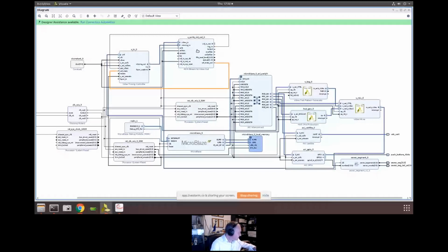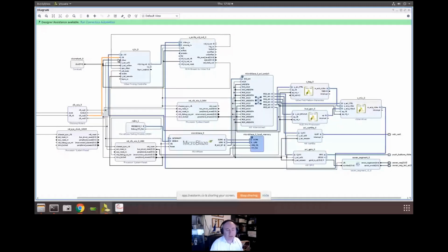And then what are we going to do? Once we've got all that done, we're going to connect the clock here. So far we've not used clock 2. So we're going to connect clock 2 here to the clock here. This is the 25 meg clock, the pixel clock.